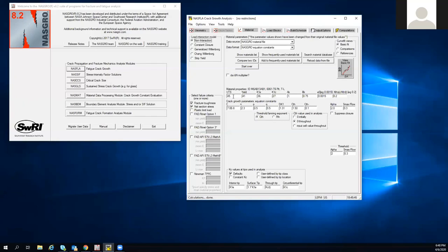In a lot of fatigue crack growth, we apply scatter factors to the number of service lives that you have to demonstrate you can survive, and that scatter factor is particularly to cover the material variability. And for that reason, it's typical in multiple industries that you actually use nominal or average properties in your fracture analysis instead of minimum properties. So that was a lesson that I had learned pretty early on.